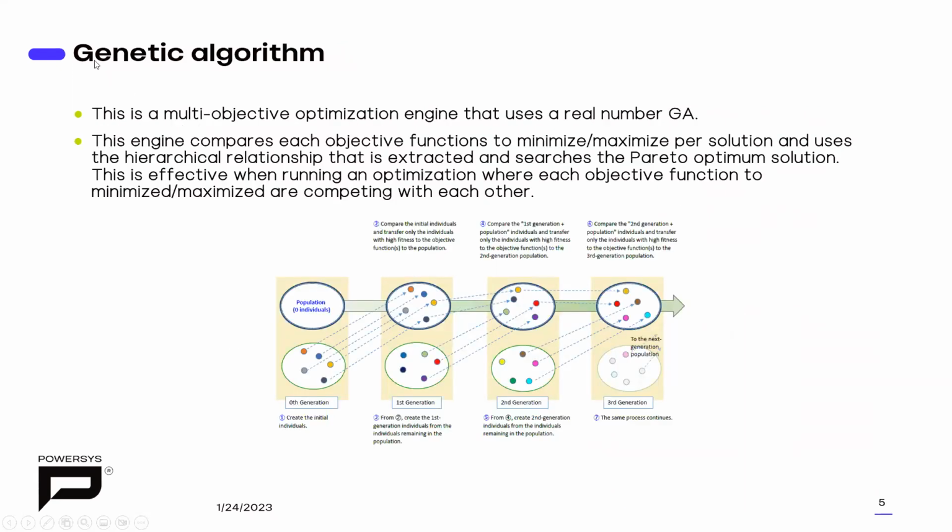So we are going to introduce some genetic algorithm, which is also a multi-objective optimization engine. Okay, but this time, this genetic algorithm will be used not only in the main optimization process, but in the creation of the shape, trying to get the minimum and maximum of each design parameter to get a valid shape, a valid geometry, with no region overlapping or something like that. No geometry collapsing.